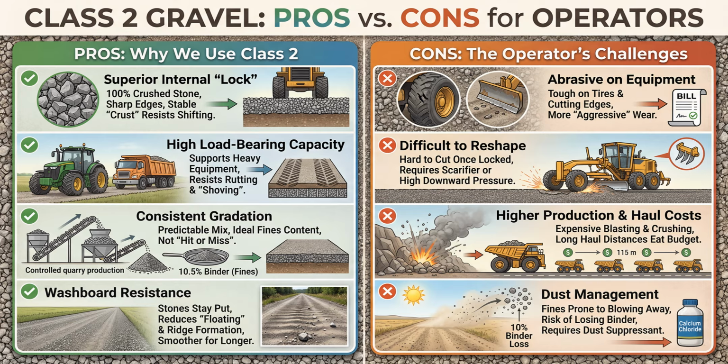High load-bearing capacity. It is the heavyweight of surfacing. The angularity of the rock allows it to support heavy agricultural equipment and tandem trucks without rutting or shoving as easily as rounded stone. Consistent gradation.